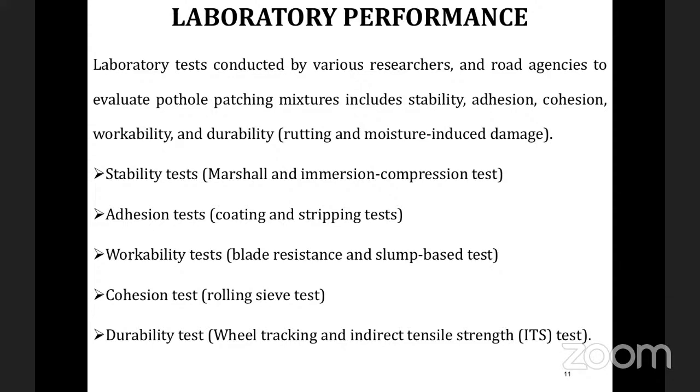Dry condition means we will not condition it; we will prepare the sample and assess the ITS value directly. Wet condition means we will go for alternate freeze and thaw cycles. That is, we will keep it in the freezer for 18 hours at minus 16 degrees Celsius, and in the water bath at 60 degrees Celsius for 24 hours, then we will assess the indirect tensile strength. Based on the ITS test, we will calculate the TSR and assess the moisture induced damage, and that TSR value should be more than 85%.